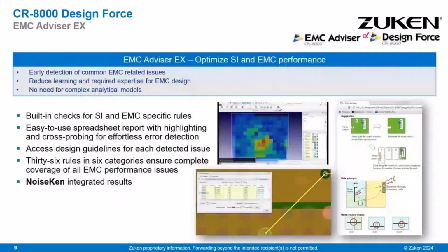Now, last but certainly not least, we have the EMC Advisor EX, which is integrated into the CR-8000 DesignForce to help identify and resolve electromagnetic compatibility and signal integrity issues. This tool provides built-in checks for SI and EMC specific rules, ensuring that designs meet performance standards. It features a user-friendly spreadsheet report which highlights errors and allows us to cross-probe directly to the layout, making error detection quick and easy.